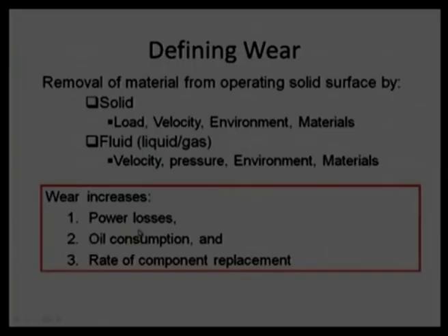So, if wear increases, the power losses, the friction losses will increase, because there is wear of the surface. And here I am talking about the measurable wear. I am not talking about the zero wear, or the initial wear, where the asperities are getting damaged or deformed or displaced for the betterment. If that kind of wear occurs, that is good for us, good for our machine.